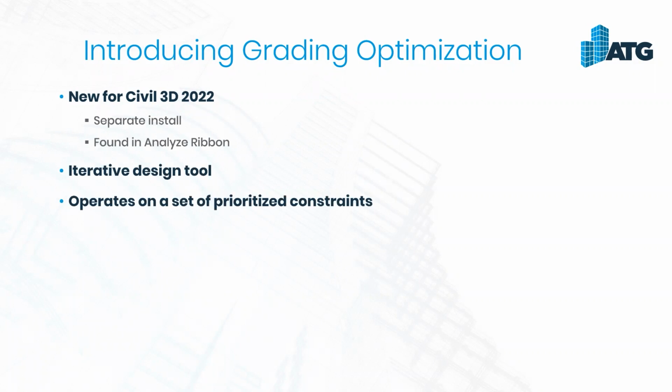So we're going to develop a set of prioritized constraints. We're going to set up where our outer boundary for our whole site is, where we have to stop and daylight and come in there. But then what's more important? Is it more important for our accessibility paths to be designed first, or is it more important for our curb islands to be developed first? We have full control over that, and that hierarchy is a concept that's very common in Civil 3D.